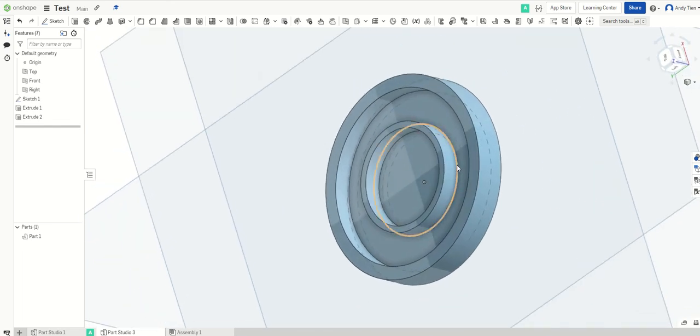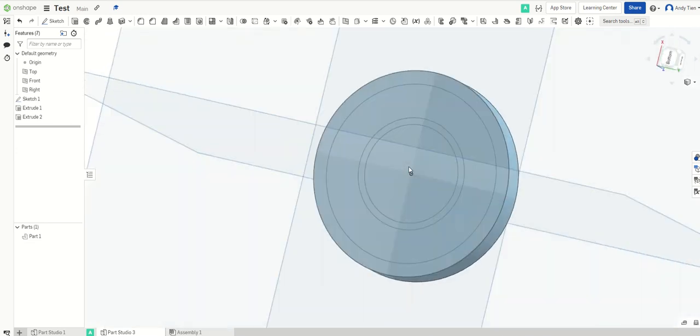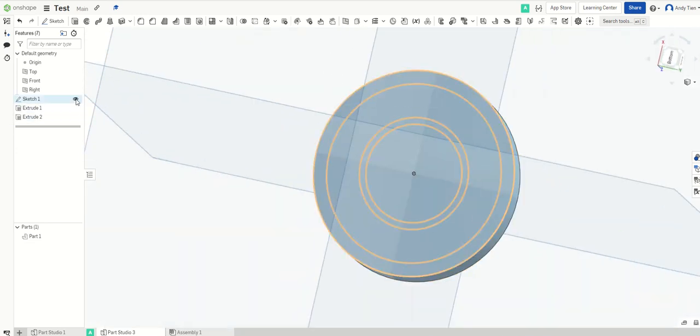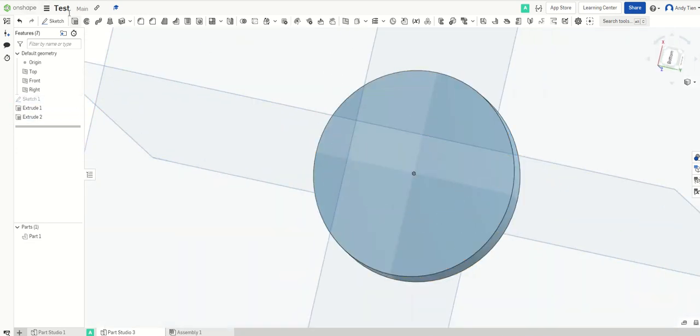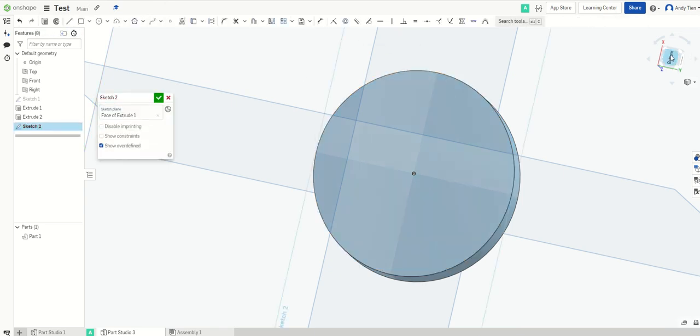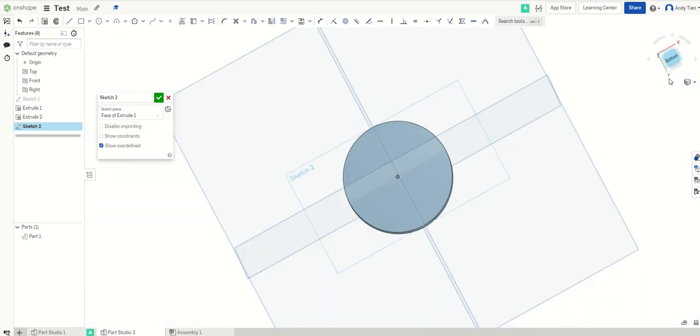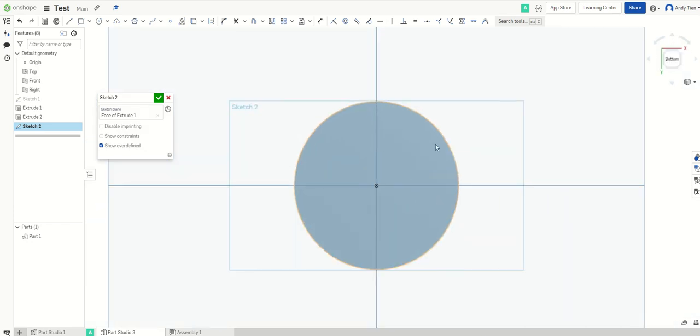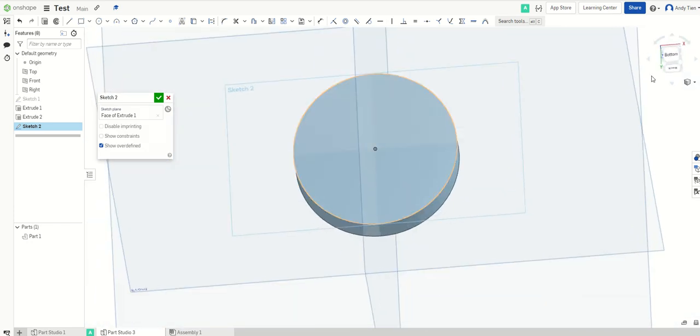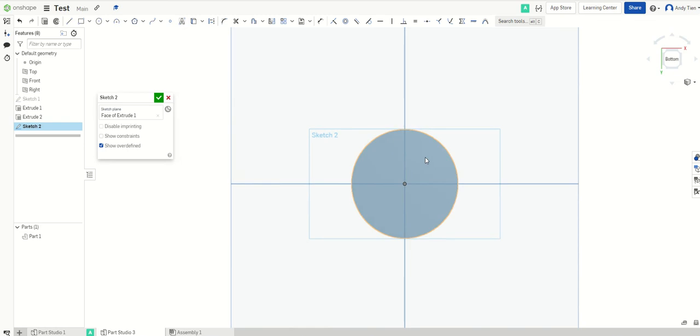So it's going to be difficult to hold this, right? So we're going to have to create something that is a tab. So you flip to the other side. Now you don't need the sketch anymore, so you can dispose of the sketch. Then you're going to come over here, you're going to click sketch, and select your plane, which is you're going to sketch on top of this bottle cap now. So what are we going to do next?